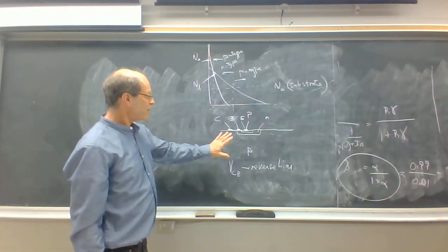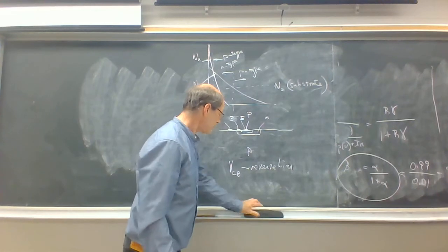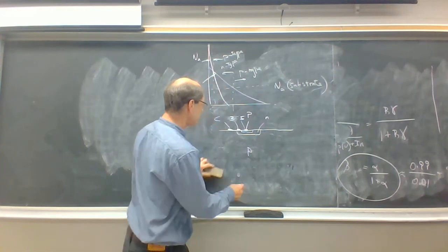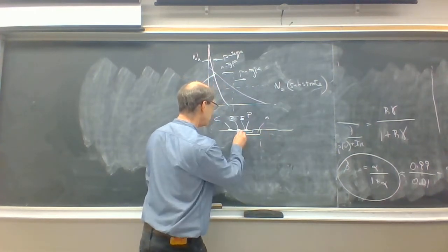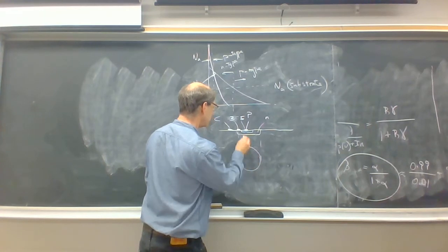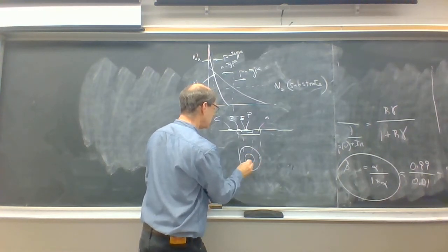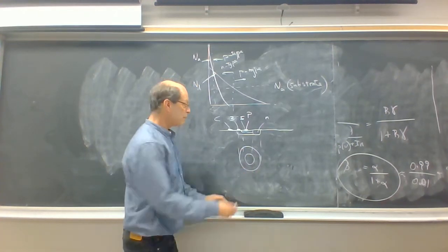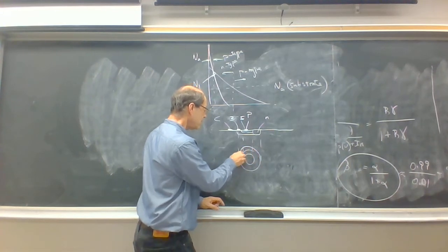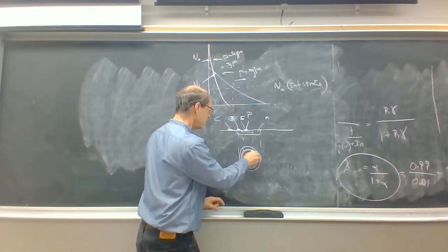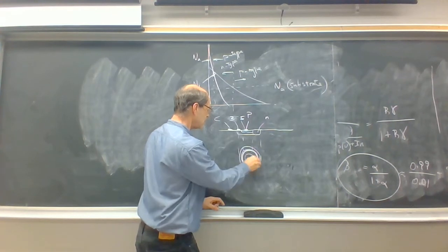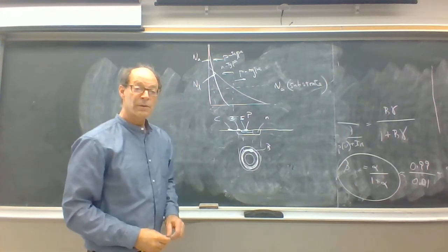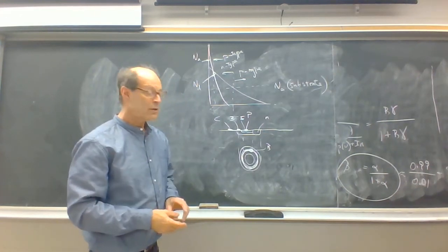If you were to look at the front view of this, or the top view of this device, it might look like this. So you can see that the base might look like a sort of donut region, and you could put the base electrode all the way around this donut. So this could be metallized in a circle, and then you could connect the base lead to that circle which connects to that entire ring of base material.